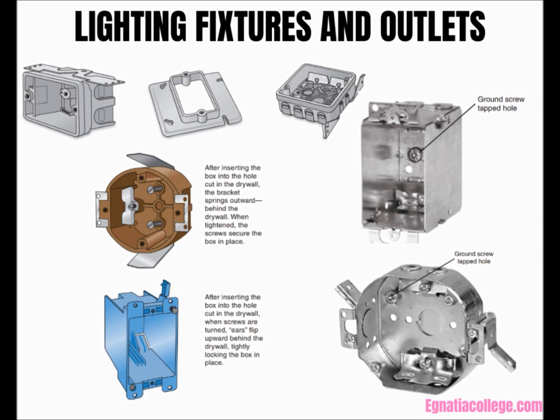A box must be installed at each outlet or switch location, Rule 12-3001. There are exceptions to this rule, but in general, they relate to special manufactured wiring systems where the box is an integral part of the system. For standard wiring methods, such as cable or conduit, a box is usually required. Figures illustrate types of non-metallic and metallic boxes.